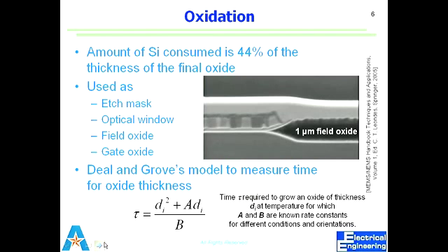When I say recipe, it means you have BHF, you have HF first, which is diluted to some concentration, and then you have to use it in certain containers, right? Because BHF etches silicon dioxide, and what is silicon dioxide? Glass, right?